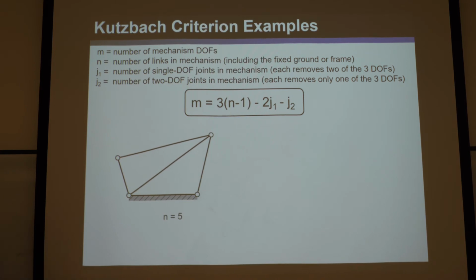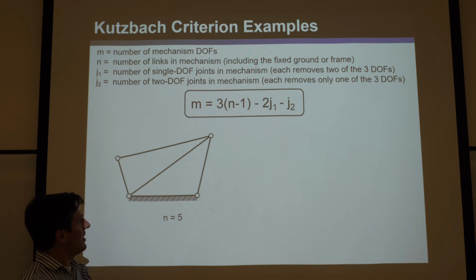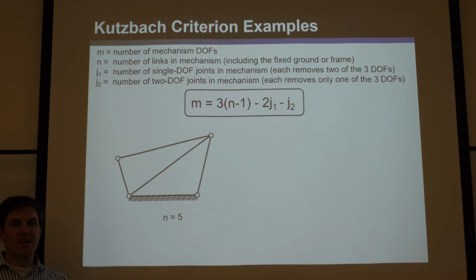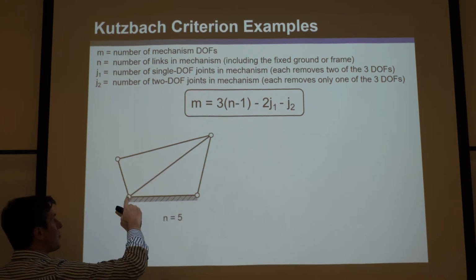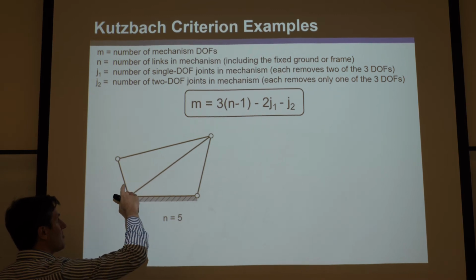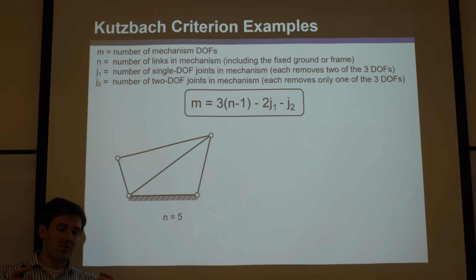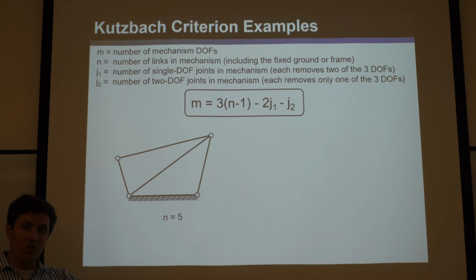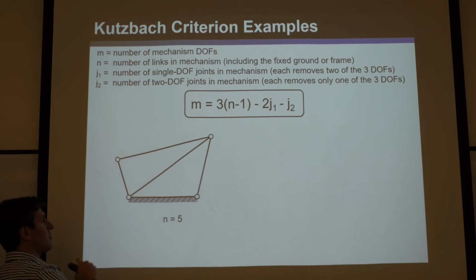Great. Well, how many J1s are there? You probably think there's 1, 2, 3, 4, but that's wrong. Remember, a joint is always a thing that just joins 2 things. It looks like, for instance, for this one, there are 3 links that this joint joins. But really, joints are called pairs because they only join 2 things. They link 2 things together, a pair. So you'd have to count this one twice.